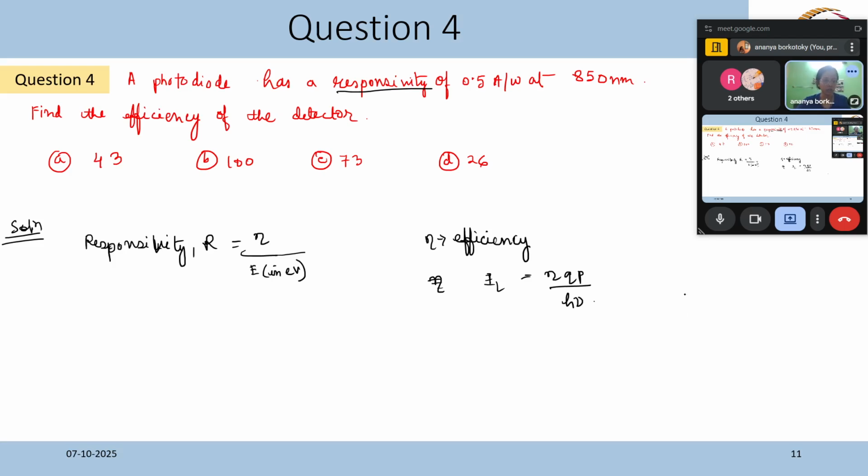So what current do we want? All the photons that are coming, creating our flux, whatever the photon flux, is multiplied by Q. Ideally we want this current, where all the photons are responsible for the photocurrent. We don't get that, we have some less current, and that is the quantum efficiency of the device.